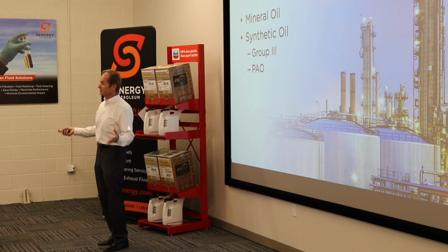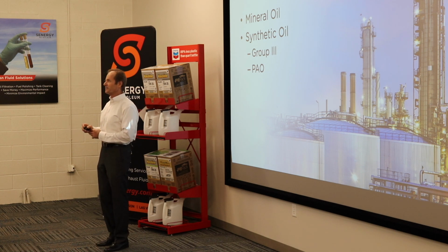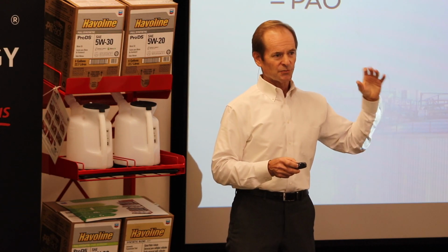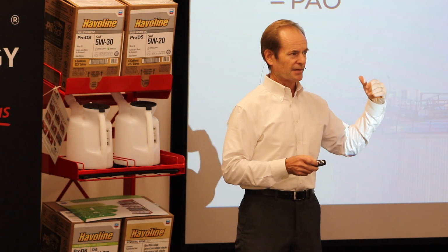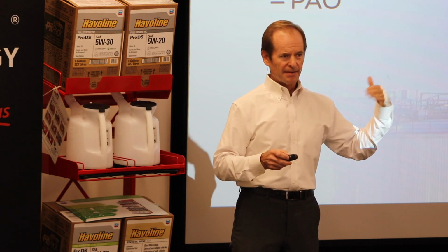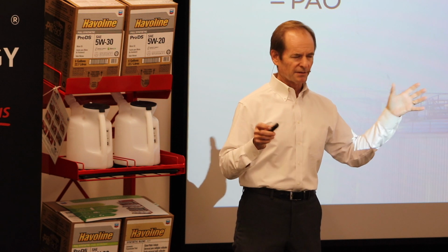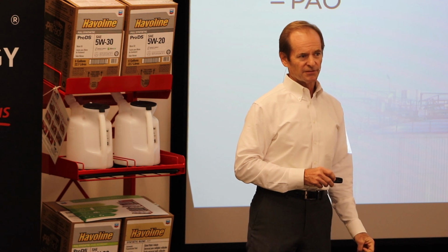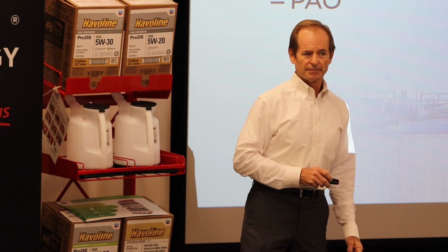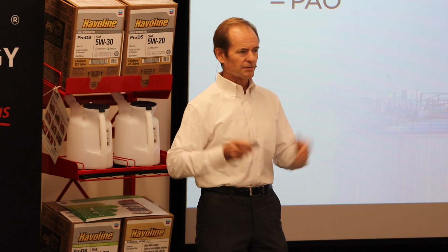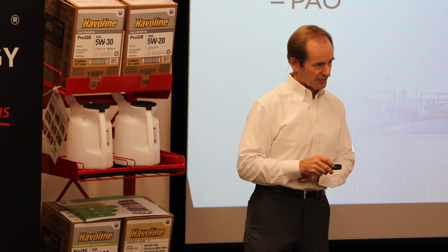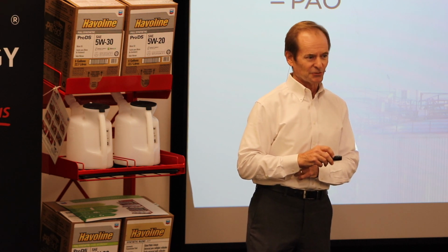Does it matter? Well, maybe and maybe not. On a lab basis, you have to work to see the difference between the two synthetics. They are chemically different, but on the lab basis and on test benches, you really have to work to tell the difference. But group 3 synthetics are much less expensive than the PAO types. That's why they're the ones that are used in the majority of synthetic engine oils. Yes, Rich? They both still get dirty when you use them. That's very true. And they get dirty at the same rate when you use them. Yep.